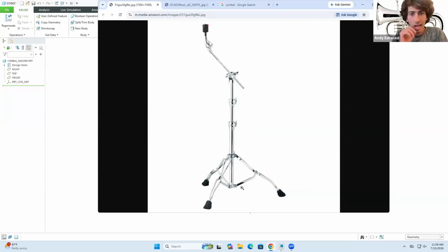The strategy that I like to employ whenever I have a complex looking assembly like this, I mean, this is not too difficult to do, it's not going to be that many parts, but there's a good strategy that could be useful for you guys in the future. You have this picture in here, and what I'm going to do is create a sketch first of the overall outline of this thing. It's a sketch that's going to have all of these tubings. It's going to have this little part in here. And we're going to always reference back to that sketch in order to create the next part. So I'm going to always create multiple copies of the same sketch.